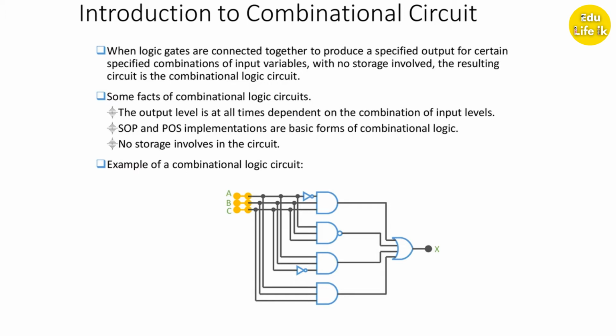Some facts of combinational logic circuit. The output level at all times depends on the combination of input levels. SOP and POS implementations are basic forms of combinational logic. No storage is involved in the circuit.